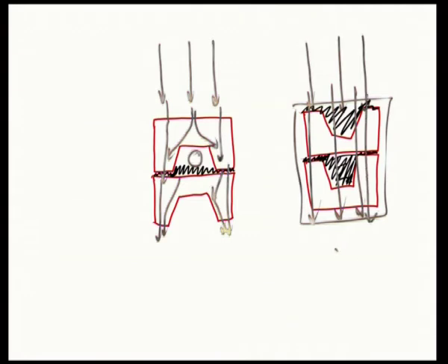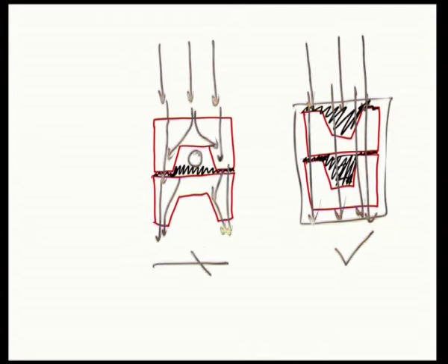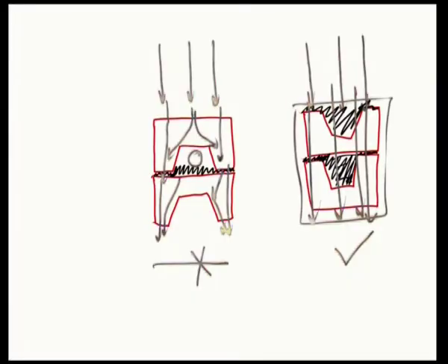So this kind of wall has more strength, is more durable, than this type of wall, because it will create some structural issues which will be minor, which can become bigger and can create cracks in the wall. That is why frogs are always laid on top while you lay your brick.